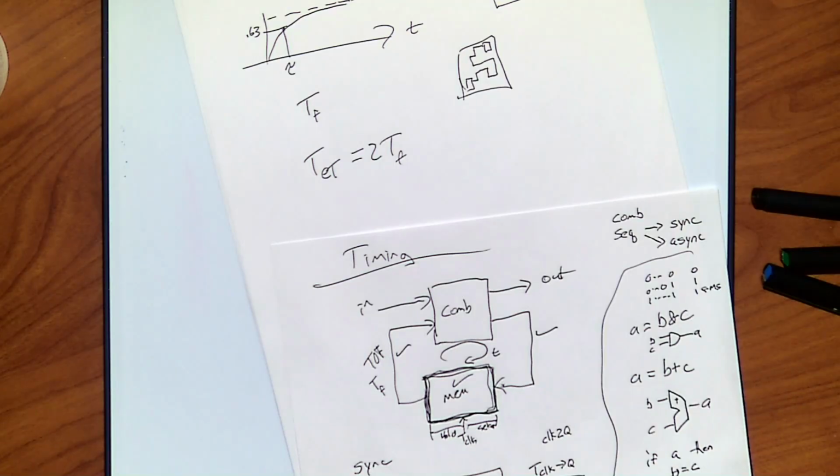Does that make sense? Therefore, for large modern systems, we don't want to use a ripple carry adder. That's why in a few weeks we're going to look at conditional sum. Instead of being linear in time, it's going to be logarithmic. Right? So log base 2 of 64 is what? 6. Right? So to go from 128 gates to 6 to 12 gates, good? Yeah, significant improvement. There are also ones that are truly linear, but what happens is a time-space complexity trade-off.